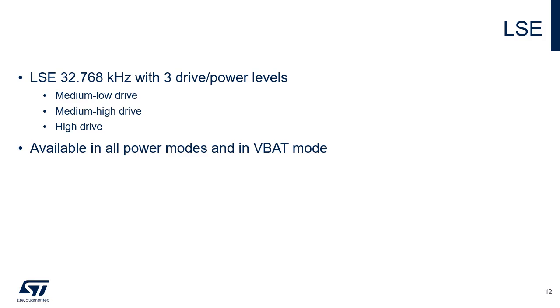The peripherals that can be clocked by the LSE are the USARTs, the UARTs, the low-power UART1, the RTC, the RNG, the HDMI CEC, the Cortex system timer, and the DAC1.